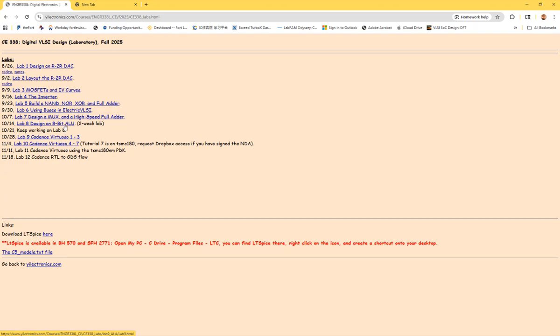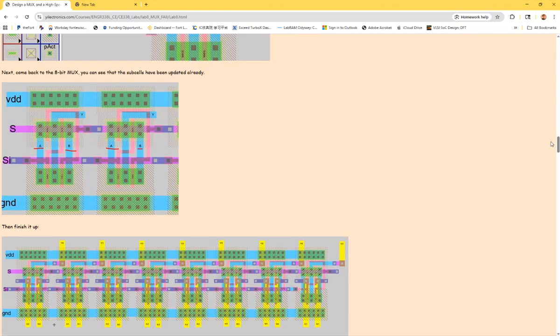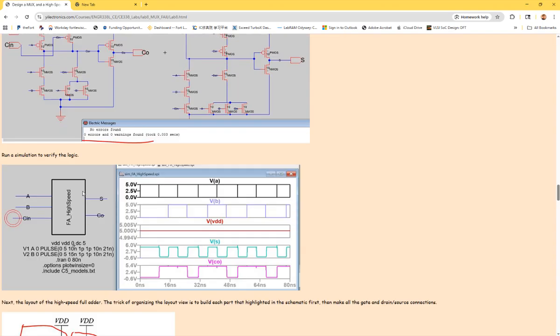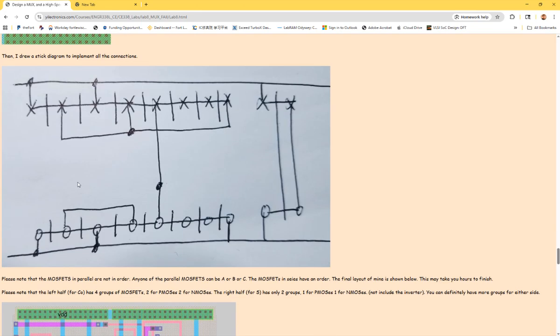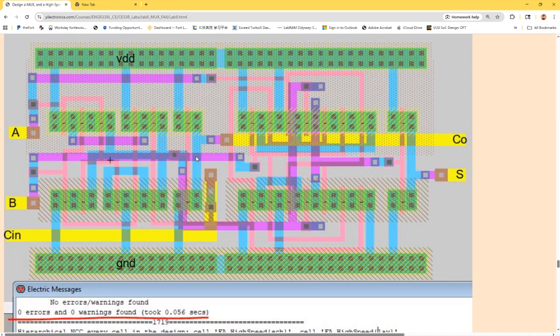Okay, let me show you one example here, not this one. This one. You'll see this a lot when you are doing the layout. Sometimes I don't have space for making a via here and going to metal one, then connecting to another poly, because, for example, I do need a connection between these two polys, these two gates,